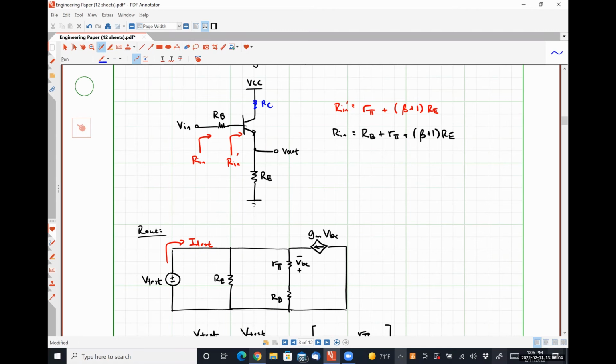Yeah. So this collector resistor effectively just stabilizes that. Or another way to think about it is if you have one of the terminals tied literally directly to the power supply voltage, that makes the transistor very sensitive to variations in the power supply voltage. That collector resistance kind of evens that out. You said it stabilizes, so you prefer to have it? Yeah, well, why wouldn't you? Okay.